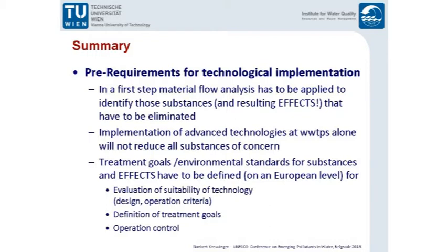Again, to evaluate the suitability of technologies, whether ozonation alone or activated carbon alone is suitable, or do we have to combine? I think that would be the direction, because ozone has the discussion with the byproducts. Activated carbon does not remove the polar substances, but we can remove the polar substances quite efficiently with ozonation. So when we have first an ozonation step and afterwards, for example, a granular activated carbon filter, then maybe that could be a really good approach.